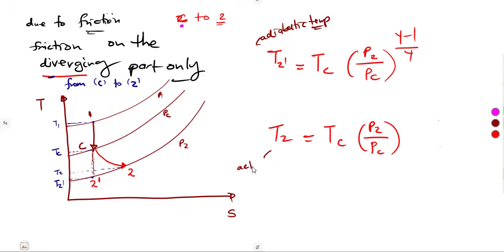If you are dealing with an actual value, you are dealing with what you refer to as the polytropic expansion. The absolute value is from the polytropic expansion. So that one is a polytropic expansion, meaning we are going to use N. Remember your gases, guys. Adiabatic, you use gamma. So that's it, just like that.